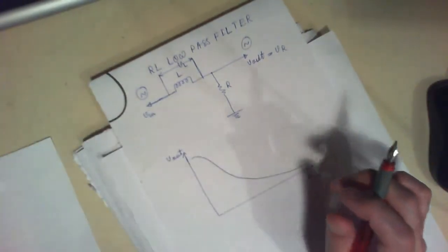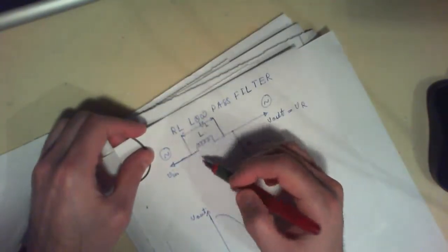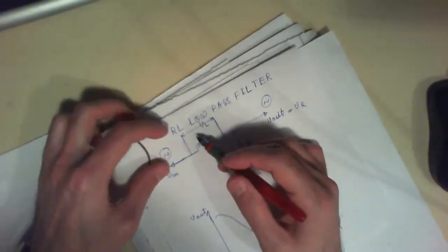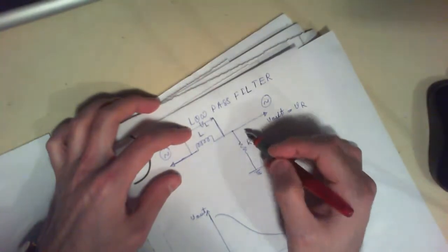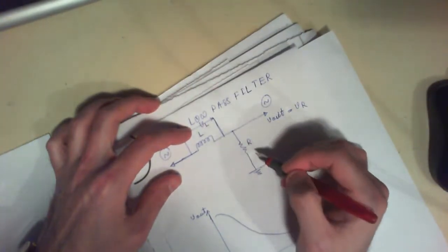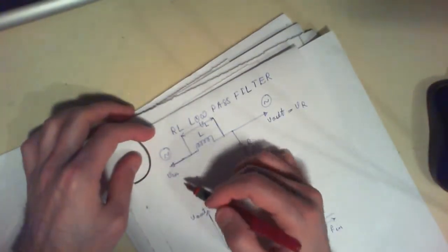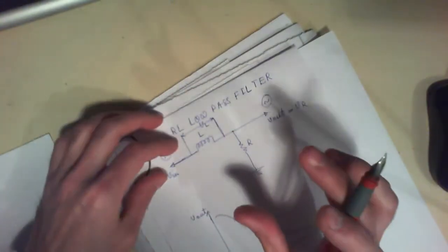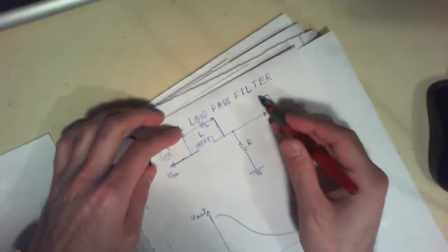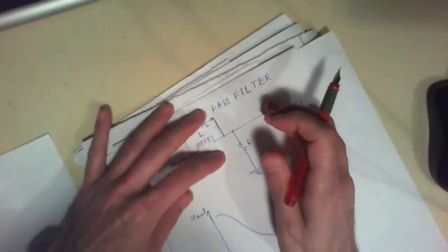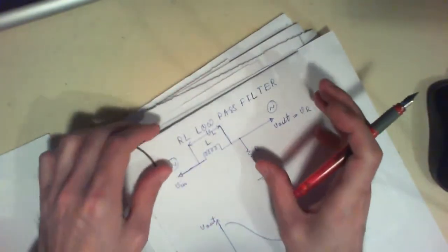So that's basically how this circuit works. Now I'm using this circuit to put the unknown inductor over here with a capacitor that I know, with a resistor that I know the resistance of. Then I'll inject some signal over here with some frequency and some peak-to-peak voltage, and then I measure the output, basically the peak-to-peak voltage over here.